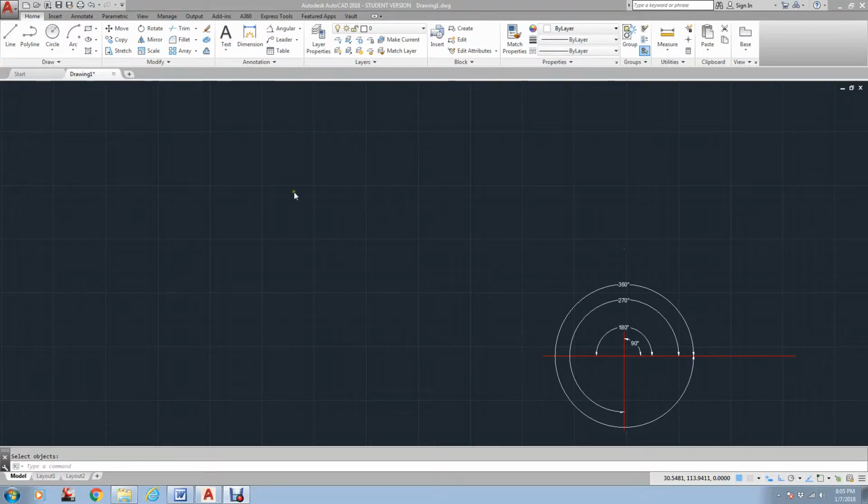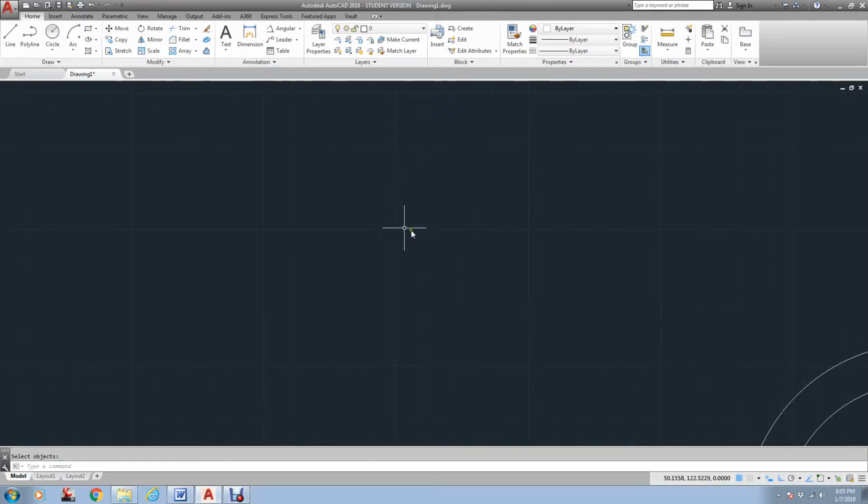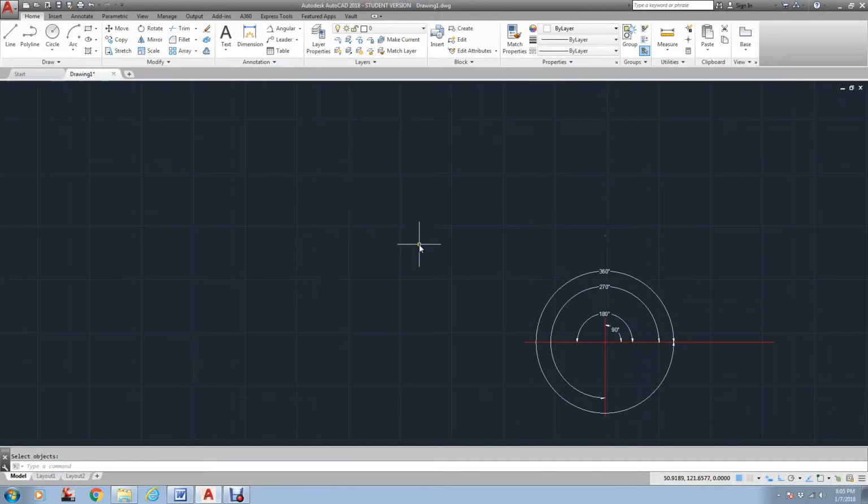I'm an instructor here in the Houston, Texas area, and this video will be covering the line command for AutoCAD 2018. And the one thing when it comes to drawing a line is understanding what information you need. Normally, when you go from point to point, that's defined. But let's just say here I'm going to start the line command. It wants a starting point.